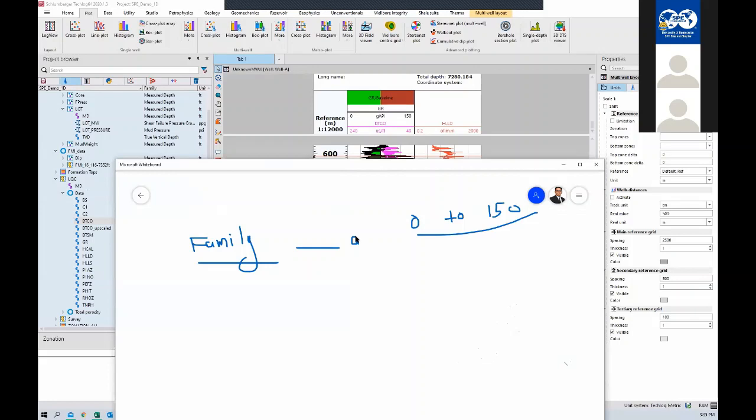It will understand the units of the density. You might have density in kg per meter cube, or you might have density in some other unit. But in order to make the software understand, you need to define a proper unit system as well as family. Understood?